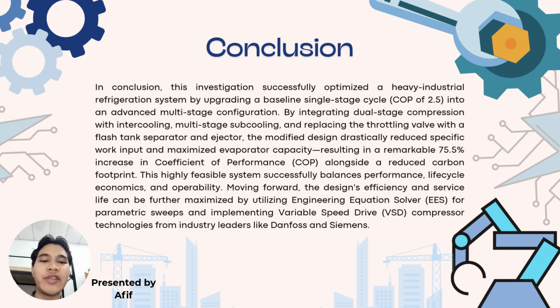The modified design drastically reduced specific power input and maximized evaporator capacity, resulting in a remarkable 75.5% increase in COP alongside a reduced carbon footprint, meaning this is a good innovation idea that we have proposed. And this highly feasible system successfully balances performance, life cycle, ergonomics, and operability, since two-stage compression is cost-effective and does not cause more mechanical failure or damage to the compressor itself.